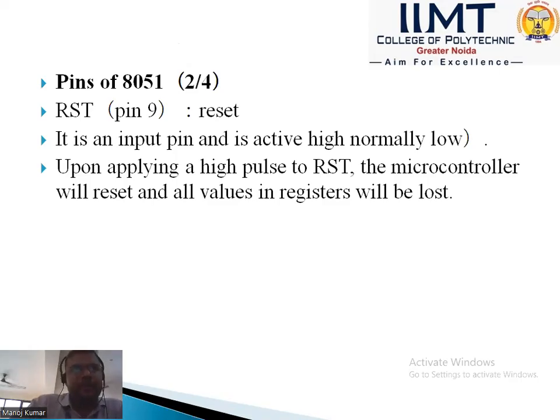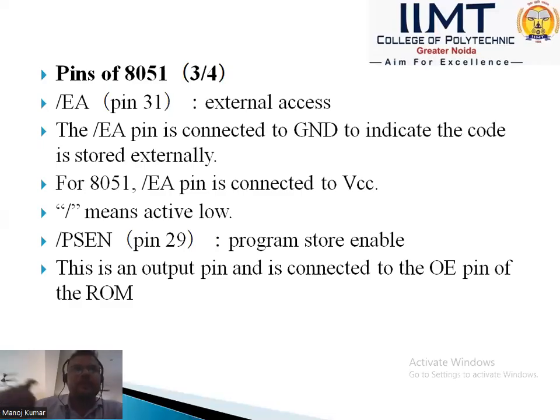Pins of the 8051: reset pin 9. Reset is an input pin, active high, normally low. Upon applying a high pulse to reset, the microcontroller will be reset and all values in the registers will be lost.